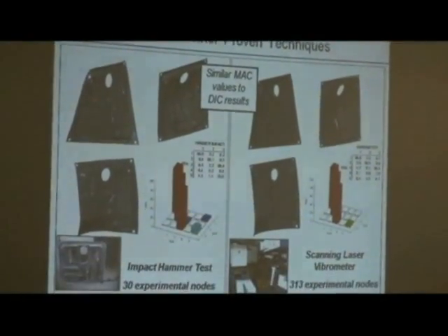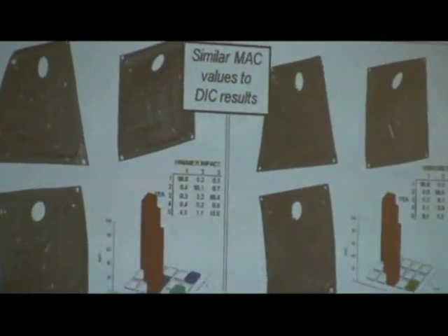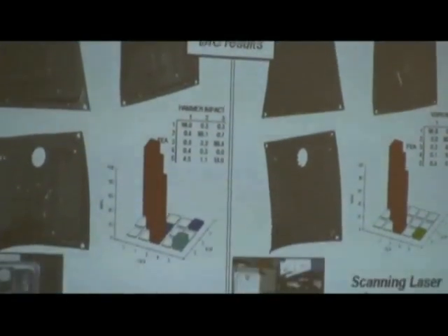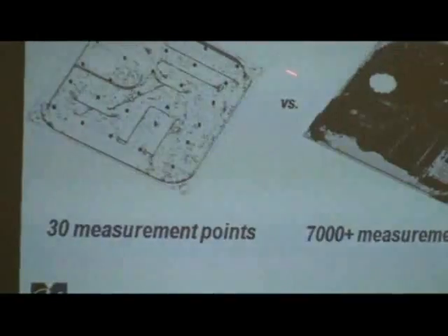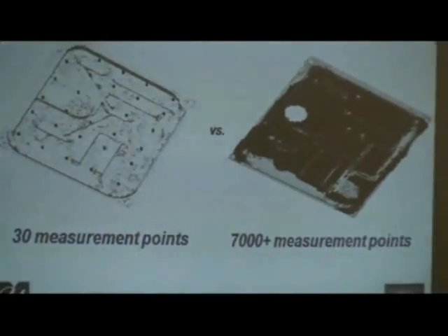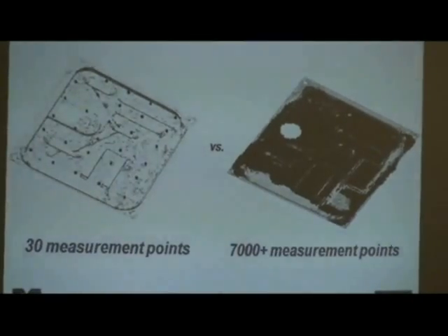And then we also compared it to other techniques. This is using an impact hammer test. This was using a scanning laser vibrometer test that we had in our lab as well. And we're getting correlations, again, 96%, 98%, etc. So it's very good correlation between the techniques.